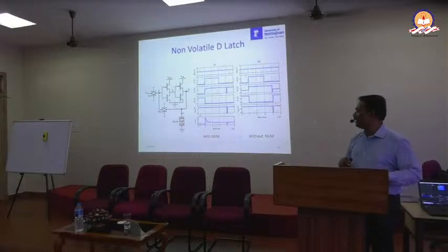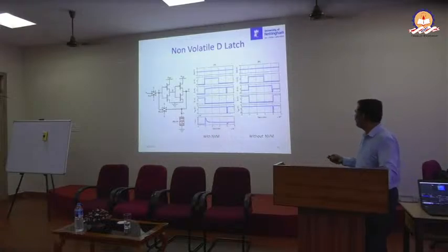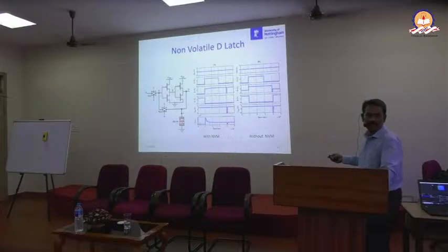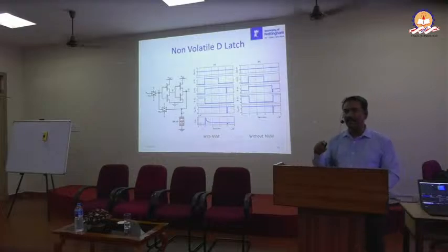I want to touch a little bit on the sequential logic. The sequential logic we introduced, you know about this, is the so-called D flip-flop, right? We introduced the memory, memristor, here. When we introduce the memristor, you can see that this is a G and this is a DM, and you can see this is a VDD. Okay, there is a small power disturbance happening to this VDD. When there is a power disturbance in VDD, you will see the data will be lost. But we are using a memristor here, so what happens with this memristor is the data actually comes back. Okay, so this is with non-volatile memory. You can see that the data here actually is coming back after the power disturbance. Whereas in the normal case, the data will not come back, it will go to 0. So by using this kind of memory in the DRAM or D flip-flop, you should be able to retain the data, even if there is a power disturbance.